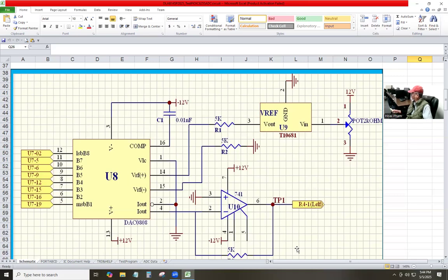So when the test fails, that is the one you have to check, and make sure U10 pin 6 is 6 volt, not something else.